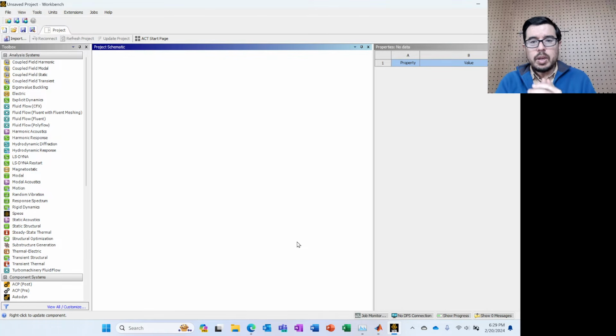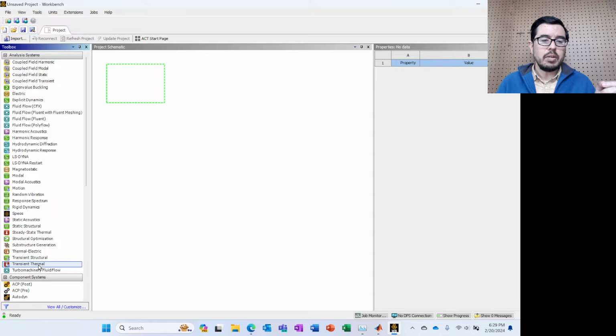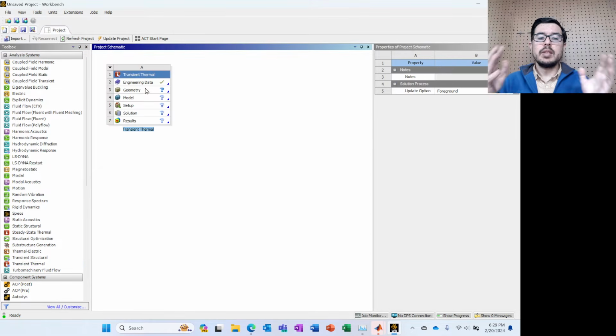When you open up Ansys, this is what you should see. And we're going to do a transient thermal problem. So if I click here, I'm just left clicking and then I'm holding it and I'm creating a standalone system. And we don't have to necessarily do all these steps in the same order with Ansys, but it's not a bad idea to go from the top to the bottom.